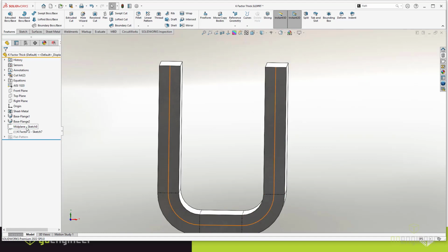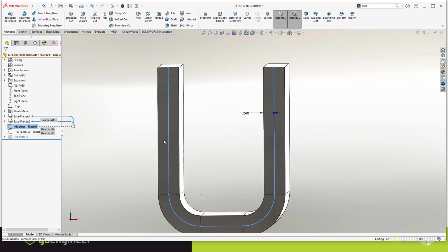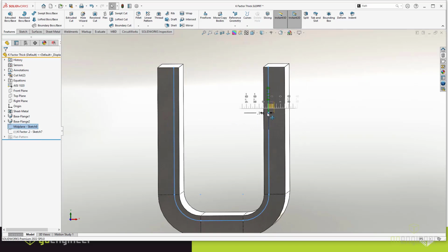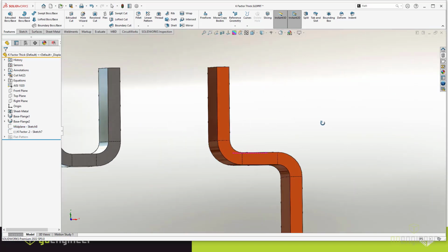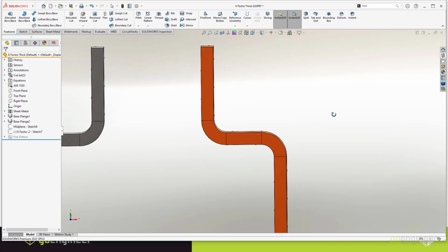Now what I was concerned with initially when I talked about K-factor being set to the inside, for example, is when you're talking about the inside bends here, it concerned me when we got to a part that was S-shaped. And the reality of it is the software knows enough to know that it's going to calculate the inside of a bend regardless of what direction that bend goes.